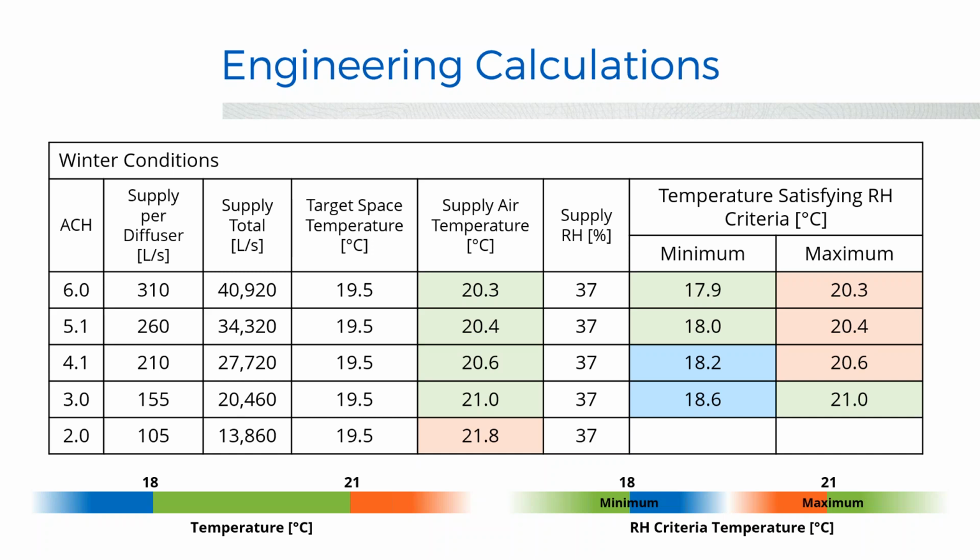The limiter of these is often the range of feasible supply air temperatures. So sometimes in order to hit an air change rate, you need to supply at a colder temperature than is physically possible from the equipment you have. Although there could also be other equipment limitations or limiting space criteria. So in this case above, we were exploring lowering the air change rate for a space with very specific temperature and relative humidity criteria, and the driving case was in the winter.